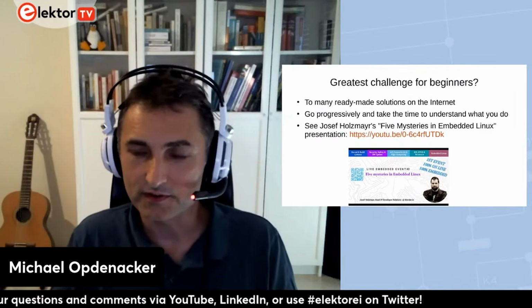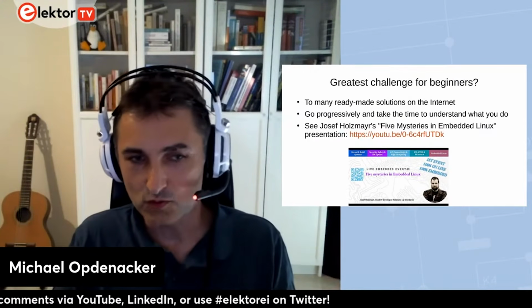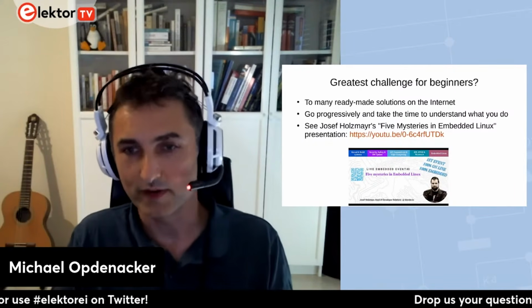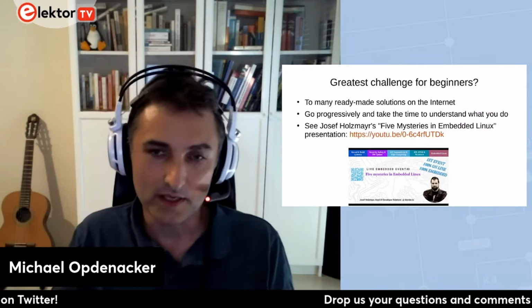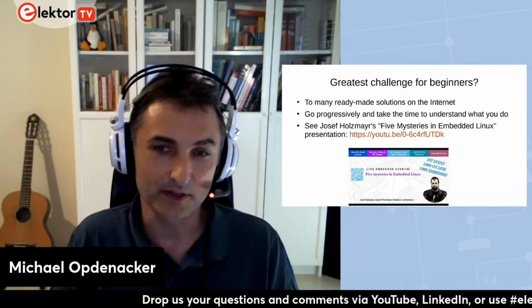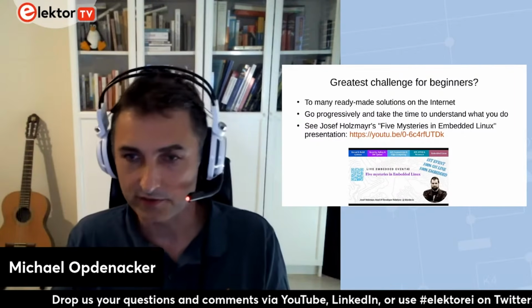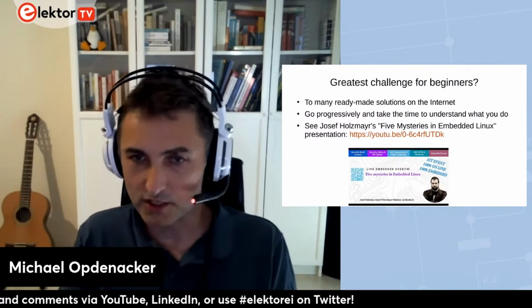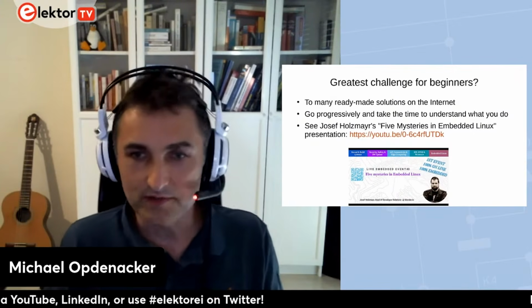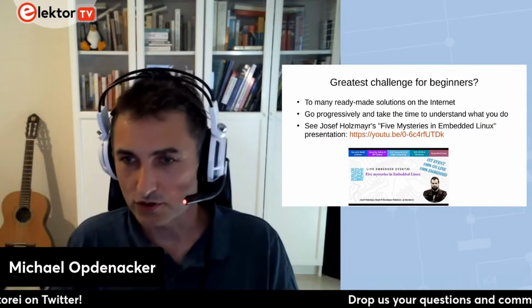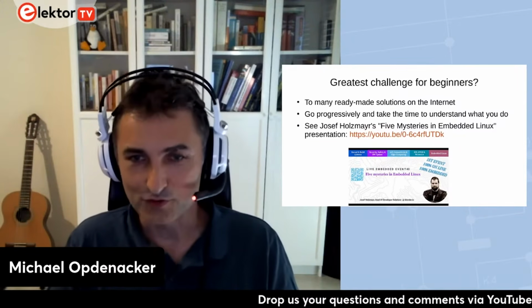But the thing is, each one comes with its own API and its own way of providing the data from the sensor, from the device, and ultimately you'll find out this is not portable at all. Every time you change the sensor, you're going to work probably with a different library, and you have to adapt your application. So ultimately, it's a good idea, as you suggested, to work with a kernel driver, a solution in the kernel.